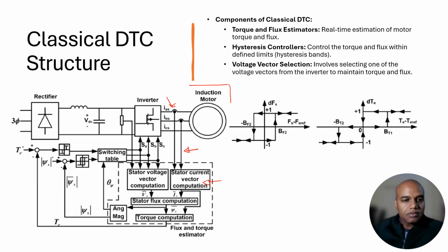Based on the modeling, which I am just giving you a glimpse of, and we will take another video in which we go into in-depth modeling, it decouples the stator flux computation and the torque computation, both. Based on the voltage measured and the current measured, it determines what the flux situation is and what the torque situation is, and the stator flux computation and the torque computation go into two separate controllers.